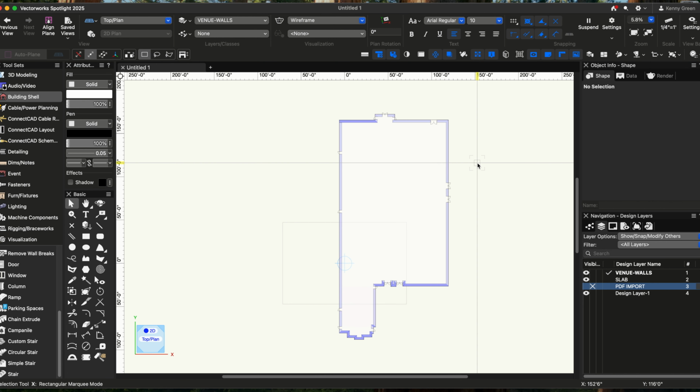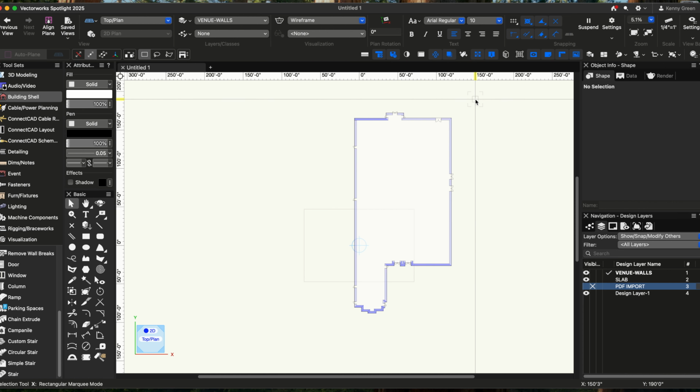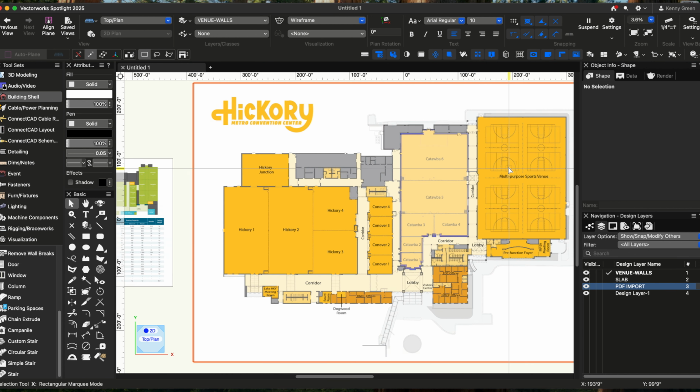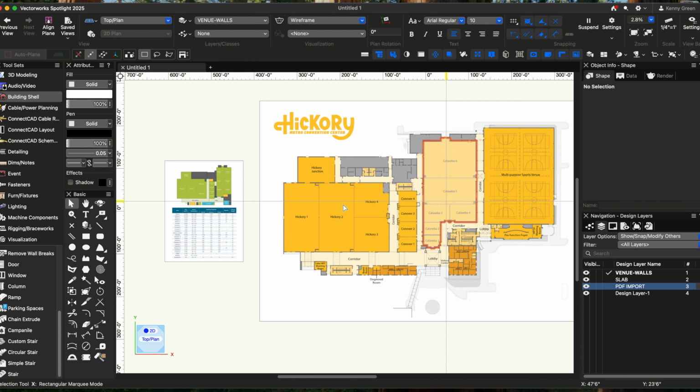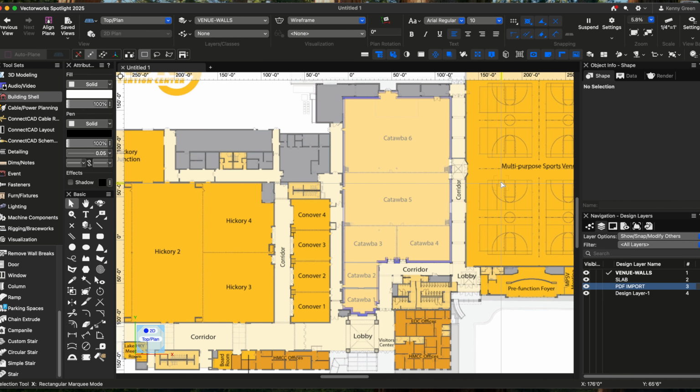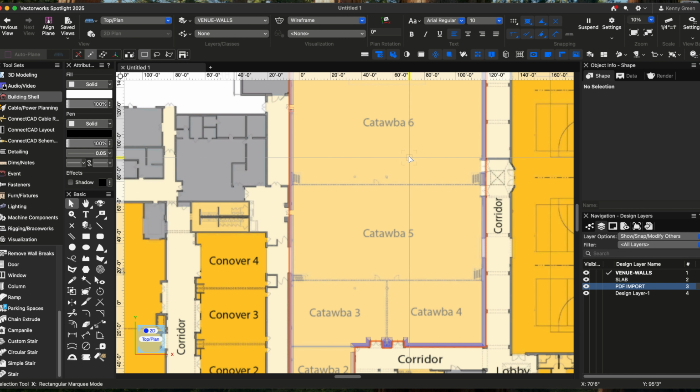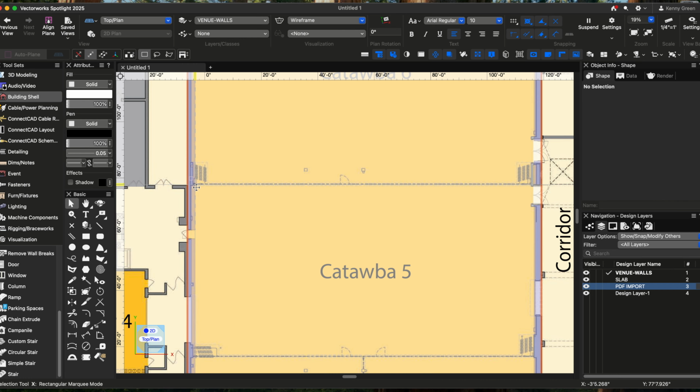So that is basically the beginning point of starting a new drawing. To recap, what we've done is we've referenced 2 different PDF documents, one that shows the facility that we're working in and another that has the data of what size the rooms are. And we drew the drawing and we scaled it. We dropped in our walls, our slab, and our doors. But one thing before we go to the next move is we're going to put in these air walls here.